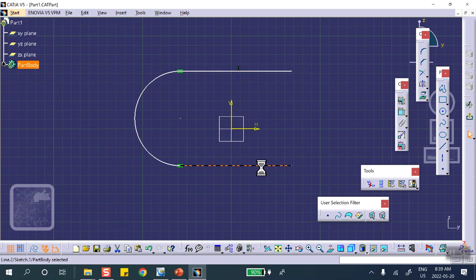Not in this problem. There is no planar symmetry in this problem, and we'll talk about that in a minute. Why are there no planes of symmetry? Because the top is clamped. The bottom, you do something else to it. The shape is symmetric, but the top right corner is clamped, and the bottom is not. If I was applying force on both sides to move this thing by 0.01 up and 0.01 down, yes, there would be a plane of symmetry, and we're going to worry about it, but not in the present model.